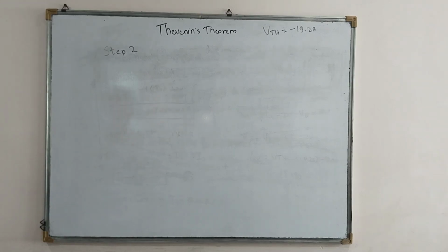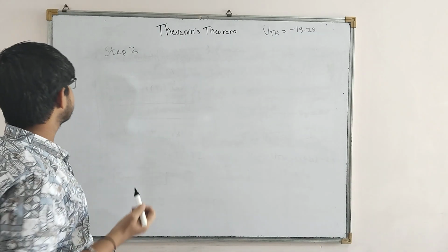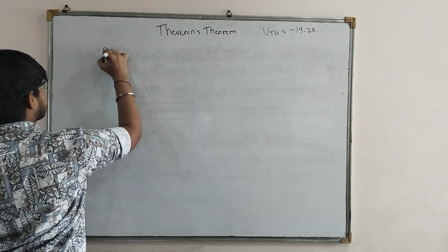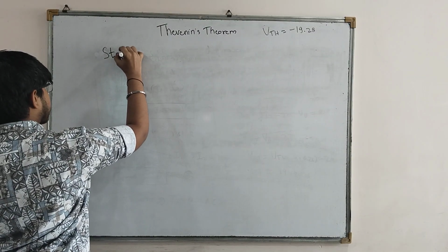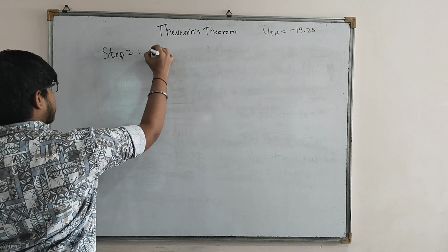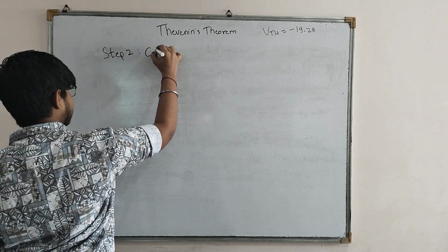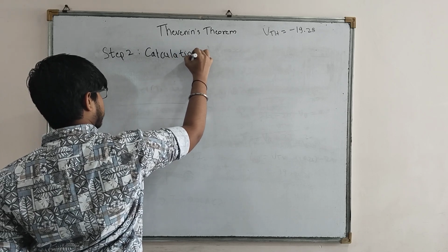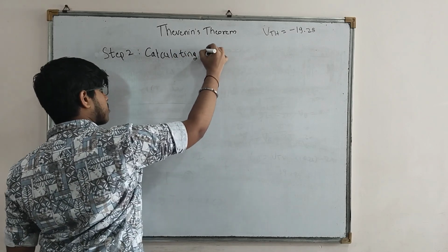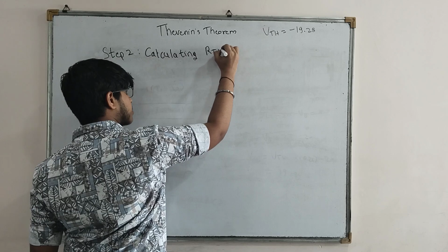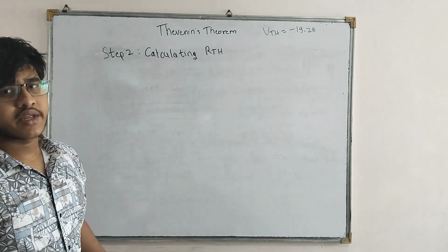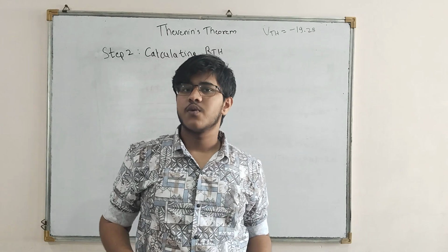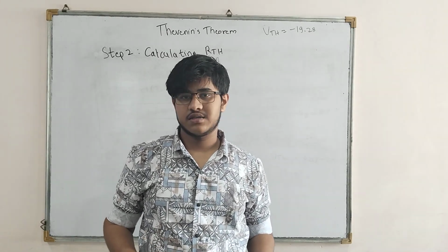Okay, I had paused the video. I was just refilling my pen. So I will just write again. Step 2: Calculating RTH. Okay, so I will draw a diagram in which we will replace all the sources with their internal resistance.